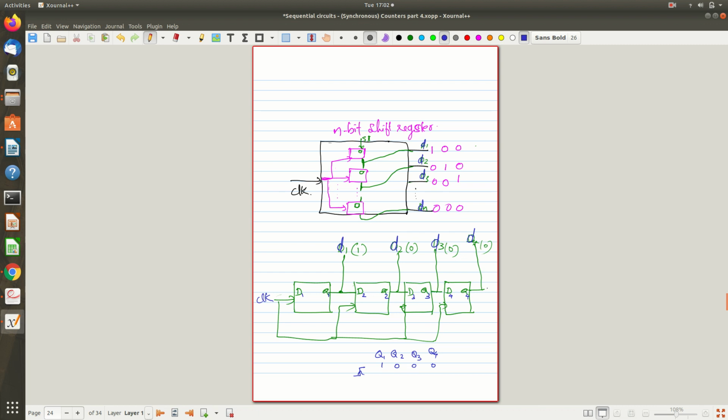Now I want to do one more thing, because this timing signal is to be produced in a systematic way. This is a further adjustment to the normal shift register: the last output of the shift register I am connecting back to the input. I didn't draw the crossing, because the lines are not touching each other. So the output of the last D flip-flop is connected back to the input, so it looks like a rotating kind of thing, shift and rotation.